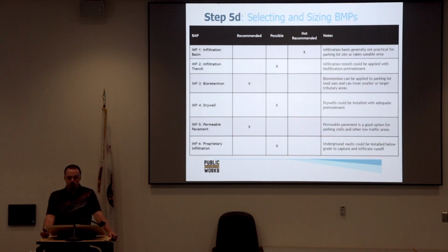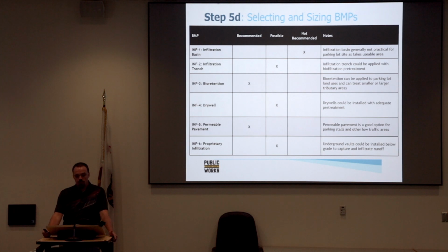So selecting from those, on here that isn't shown is infiltration 7, which is bioinfiltration. It's basically the same as infiltration 3. Infiltration 3 and infiltration 7 are essentially the same, except bioinfiltration is when you've established your soils are soil number 3 or are slightly less than 0.5 inches, but you still want to do some infiltration, and then you do have a raised underdrain.